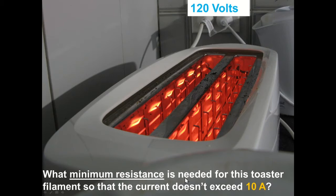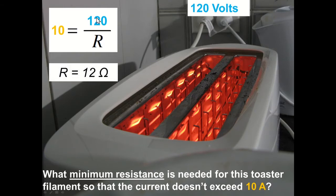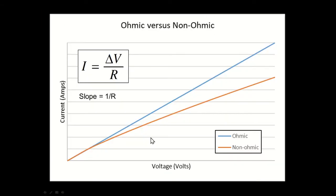What minimum resistance is needed for this toaster filament so that the current doesn't exceed 10 amps? Well, it is just plug and chug. The voltage was 120 volts. We want to have it no more than 10 amps of current. So we solve for the resistance, multiply both sides by R, divide both sides by 10. We get R by itself, and 120 divided by 10. As long as we have 12 ohms of resistance in that wire, you won't get more than 10 amps when you plug it into 120 volts.